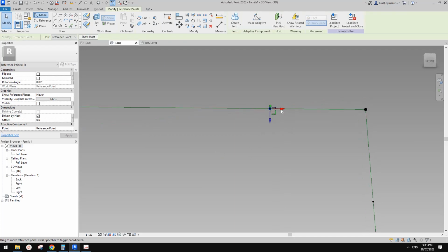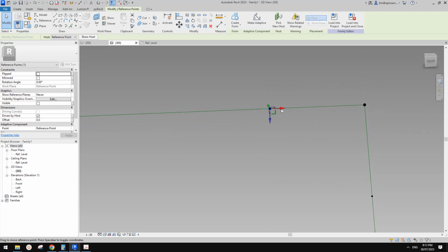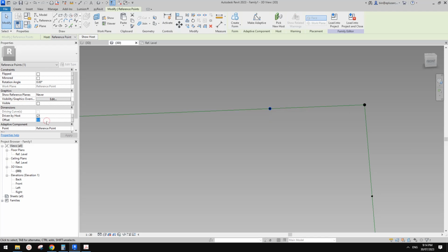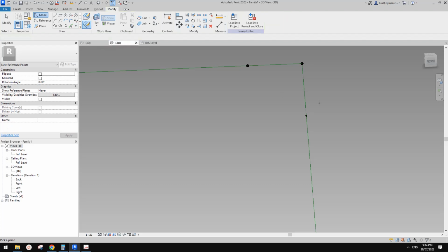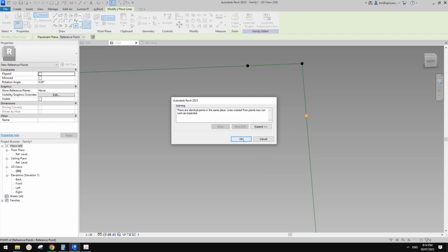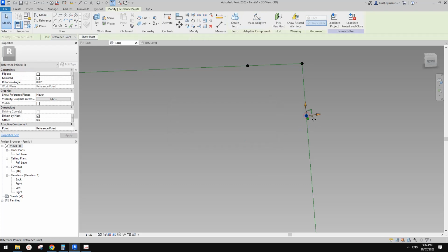So now you can see the red arrows on the right hand side, which means we just need to drag it to the left, or we can just type in a -1. Okay, so -1. Okay, so now we're going to do the same. Draw on world plane, set world plane, pick this world plane, place it on that point. Okay, escape, select. Okay, so this time we just wanted this one to go. Yeah, so it's the same. -1.